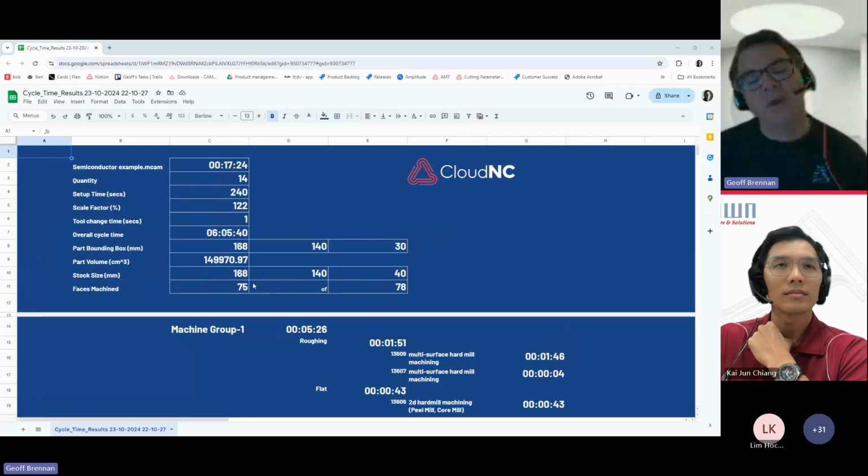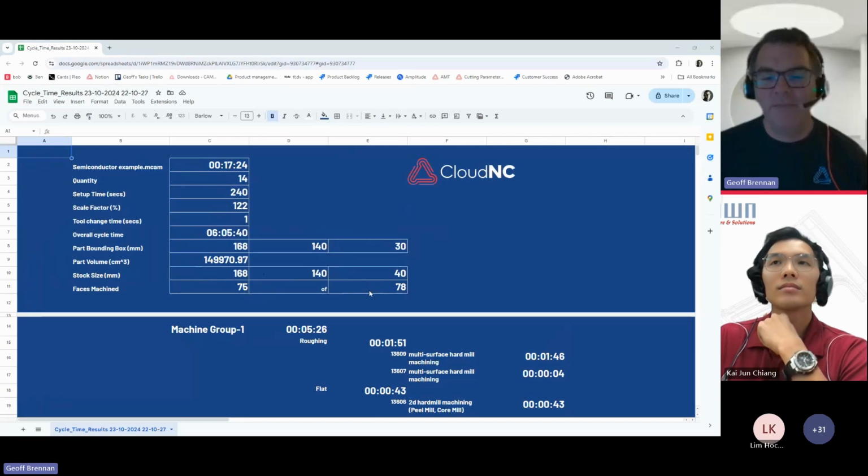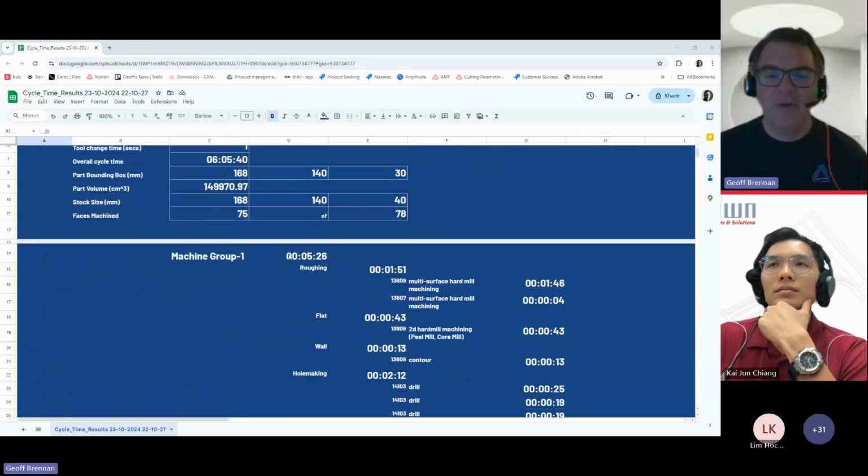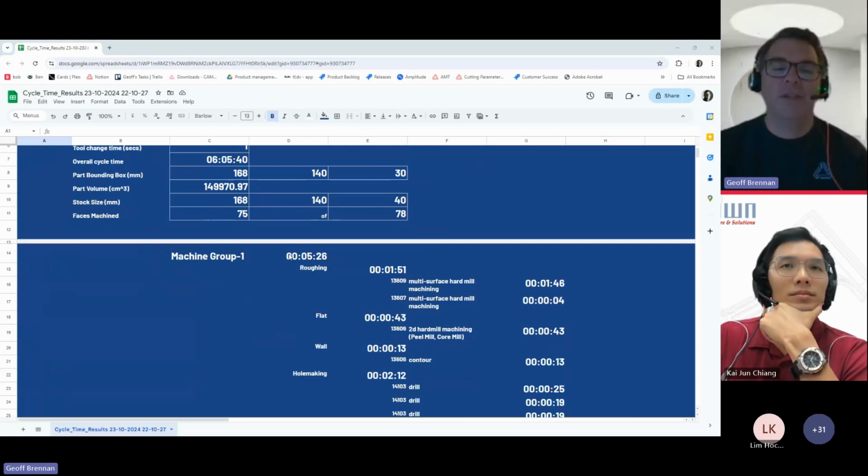So this is another one of those elements where we could sort of extrapolate that I might need to do a bit more manual operation in Mastercam to deal with those three faces. They might be incidental or not important in this case, but that's something that we go and check on. We'll see that number come up right when CamAssist completes as well, in the dialog that CamAssist is completed, it's done X number of X faces, and that'll give you an indication. Of course, if you're doing maybe a 3-axis job and you're only doing one side of the part, you'd fully expect to be less than 100% of those faces.